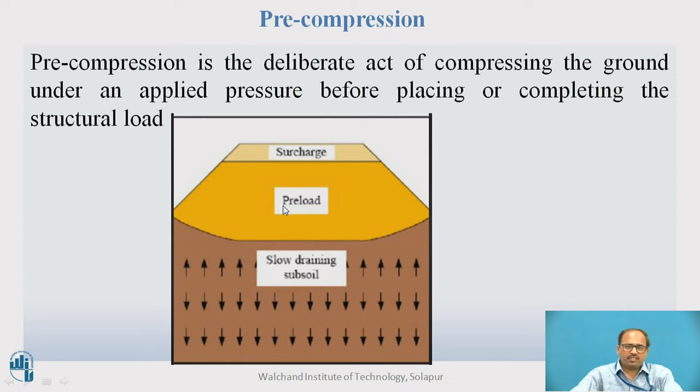Before construction of the superstructure, we will first apply some surcharge load. That load is called a surcharge load or preload, and we can call it pre-compression.